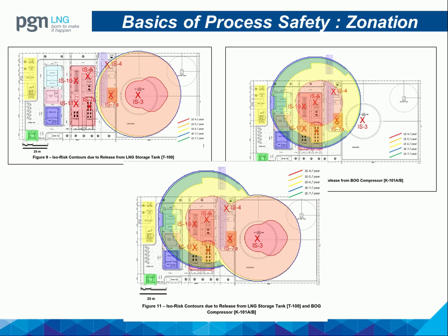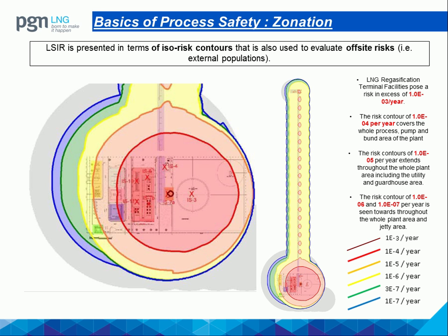It still can happen that he gets injured or suffers fatalities, but we already accept the risk that something happens to them, because the residual risk is acceptable. Again, this is a zonation. I already explained that the risk contours perhaps are around 75 meters from the fence, so there should not be anything within 75 meters of the fence.